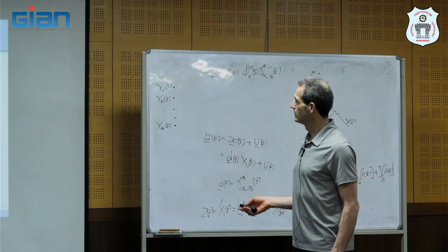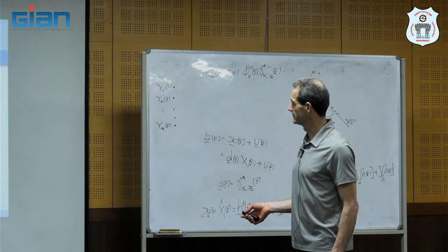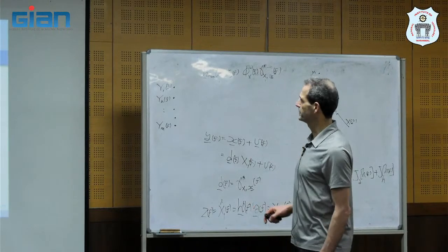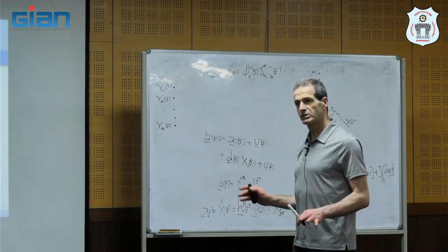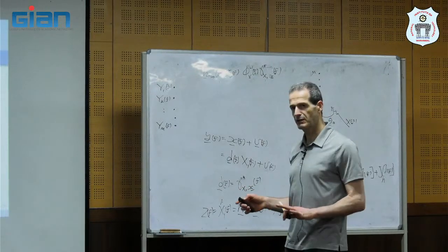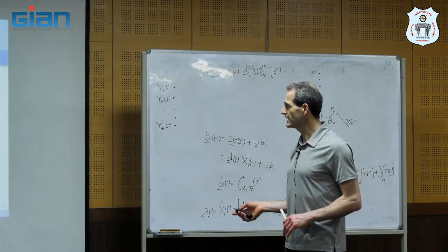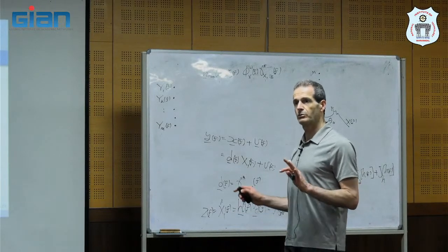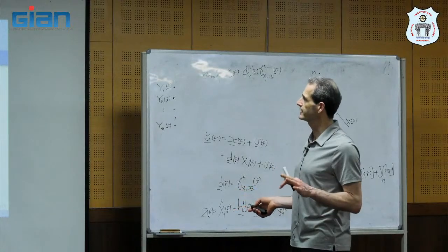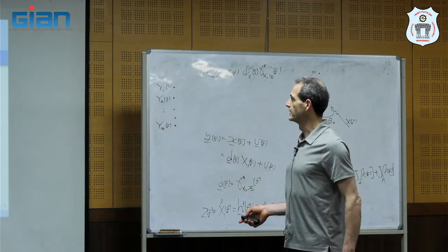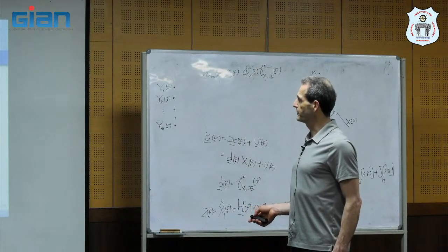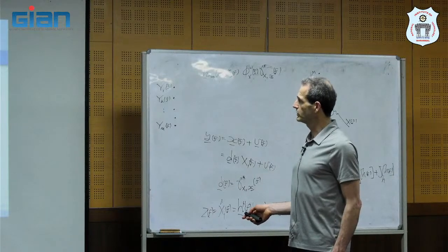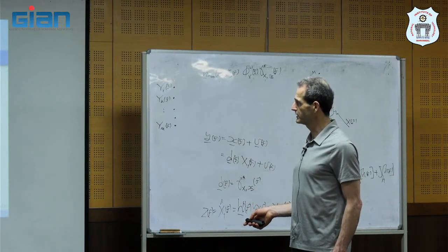So if we derive the Wiener filter, we see that it looks like this. It doesn't look proportional to phi v minus 1, so it's a question whether it maximizes or not. But we will see that we can have a different formulation of the Wiener filter. So we will continue. But here it doesn't look like it maximizes the output SNR. But we can define different things.